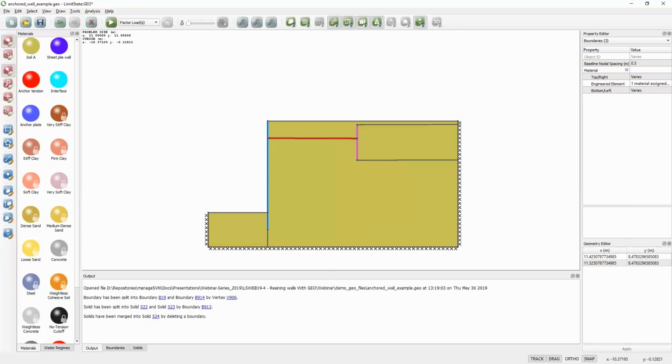So in terms of guidance, I think it's whatever keeps the geometry tidy. The analysis shouldn't really be affected by where they are, as long as you've got the same number of nodes distribution in adjacent blocks, and typically we recommend having twice the nodal density on lines, but they are set by default.